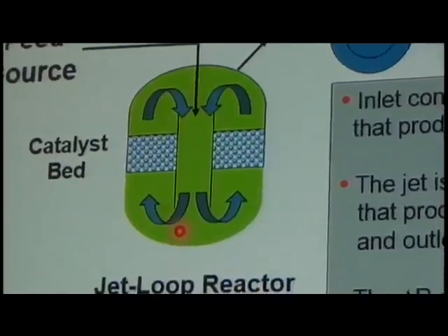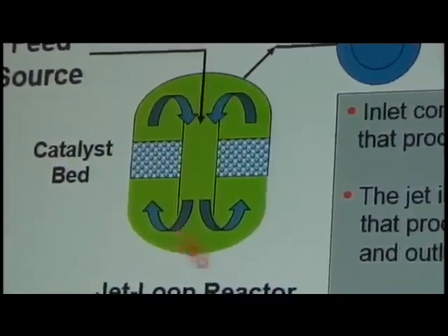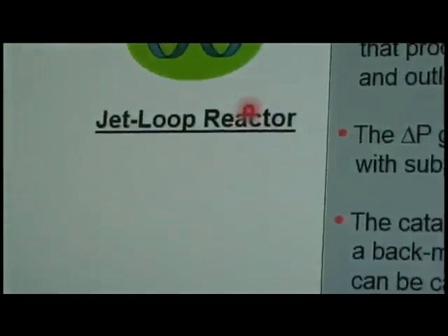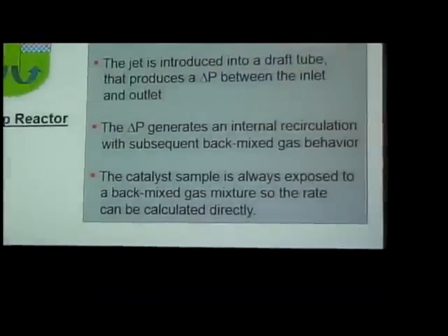And with appropriate jet and geometry design, one can create a backmix type of environment in this type of system. What's very attractive about this approach is that the reaction rate can be computed directly as the difference between the molar flows at the inlet and outlet divided by some measure of the catalyst weight, metal, or what have you.